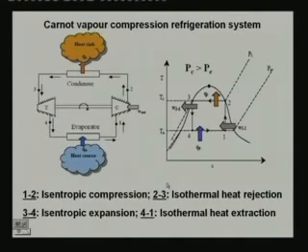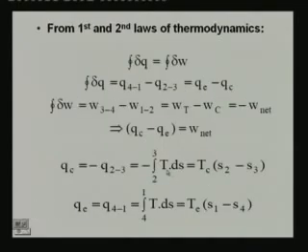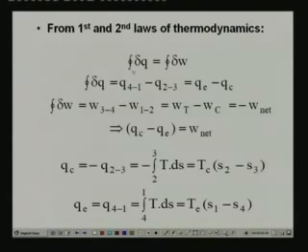Now, if you do a simple analysis of the system from the first and second laws of thermodynamics, you can write for the cycle: cyclic integral of δQ is equal to cyclic integral of δW, and δQ is nothing but the heat transfer taking place during the cycle.